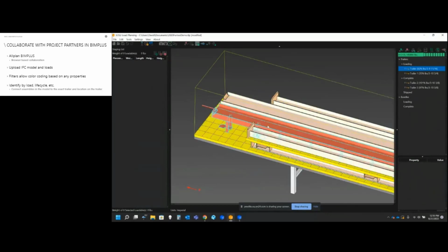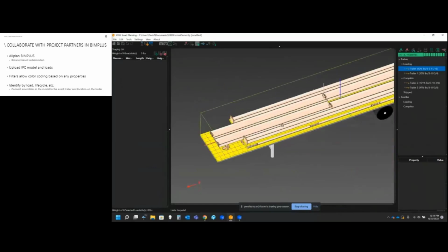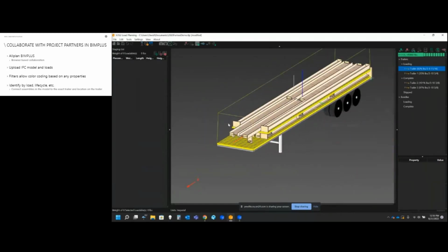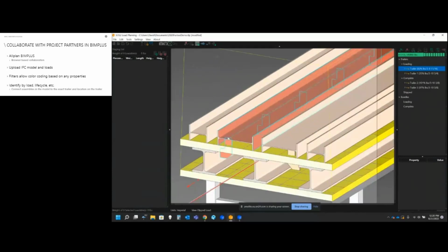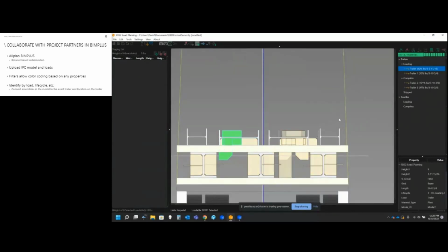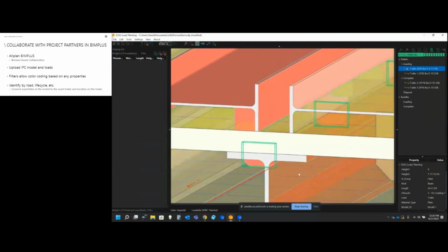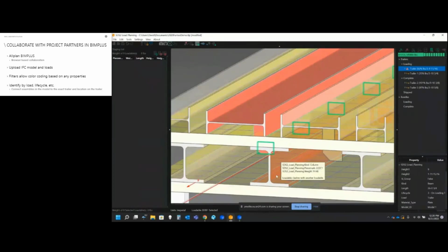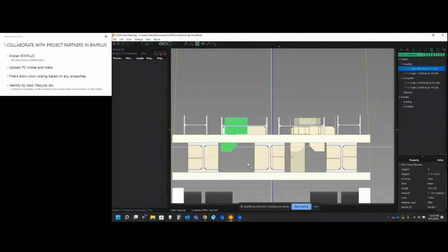So just to give you an idea, why did rotating that end for end work, but it didn't in the other case? Well, we can really start investigating some of this stuff in here, and I can even clip this view. You probably noticed when I added to the staging view over there in the model, we had some outriggers on these, right? Those are up towards the top. If I rotate it end for end, when I have it flipped this way, you can see that green box indicates there are some clashes with something down below on that lower layer. Again, rotate them end for end. We can see we've got where we can fit now.